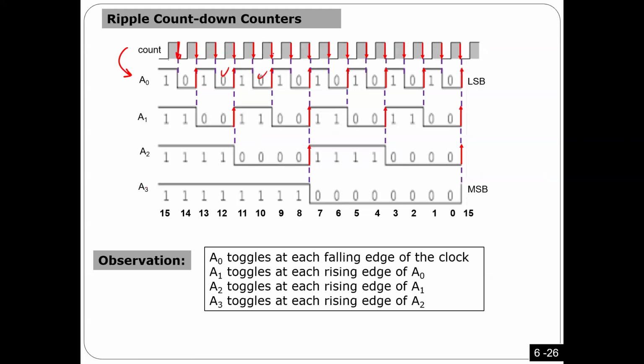Okay, so this one, the first flip-flop, is actually similar to count up. There is no difference. So the way I'm gonna connect this one is we have 1 here, and then the clock is triggered from the input source clock. The first one is exactly the same thing as count up, so it's not gonna make a difference. Every falling edge it has to toggle.